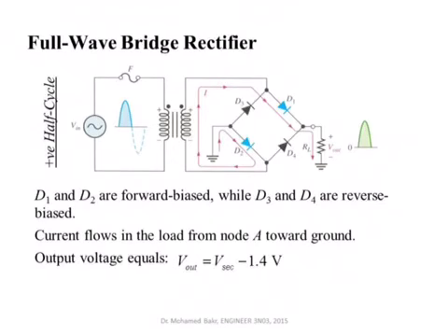Okay, well, the half-wave rectifier is not the end of the world. There are so many other rectifiers that are more efficient than the half-wave rectifier. The one that I want you to pay attention to is called the full-wave bridge rectifier. It's a very interesting one. And again, the way we have it, there is usually a transformer. It steps down from the 120 volts that we have from the outlet to, say, 15 volts or 10 volts, depending on what is the output voltage we are looking for.